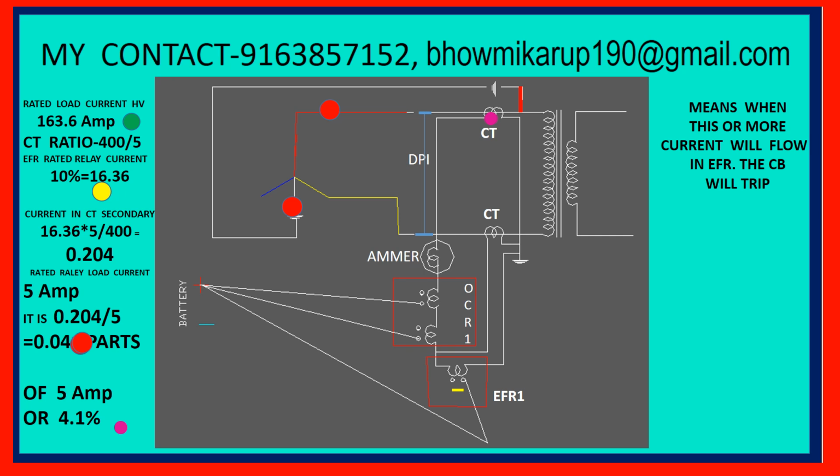One will go to the ammeter and overcurrent relay and return to the CT, but it will not trip the overcurrent relay. Why? It is not a fault current.